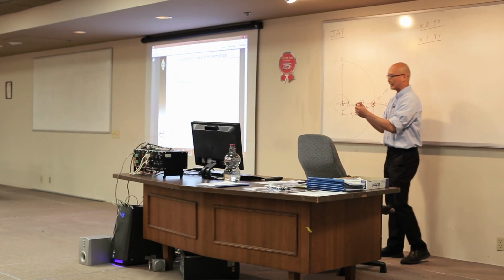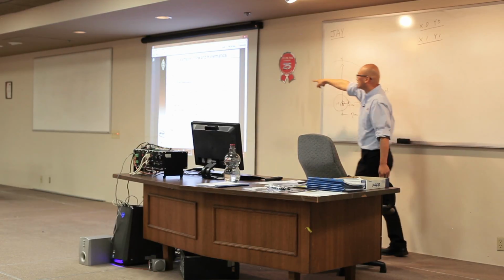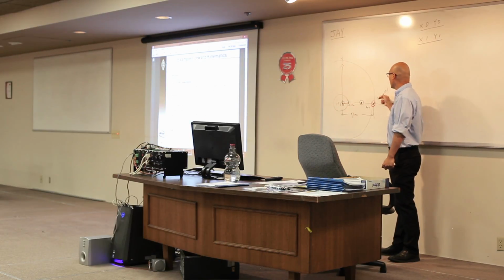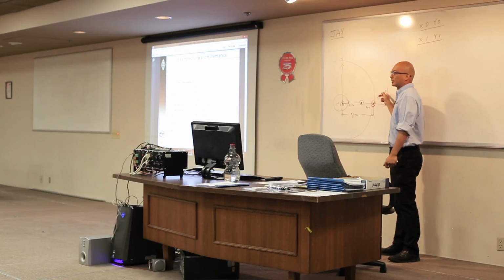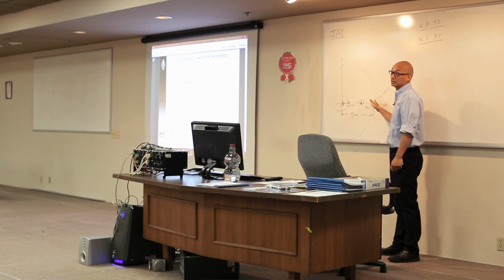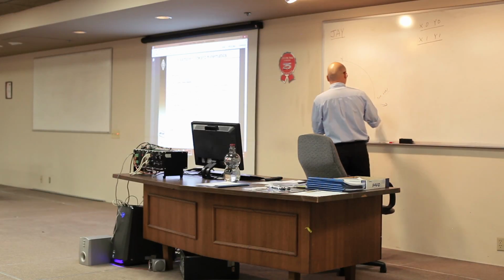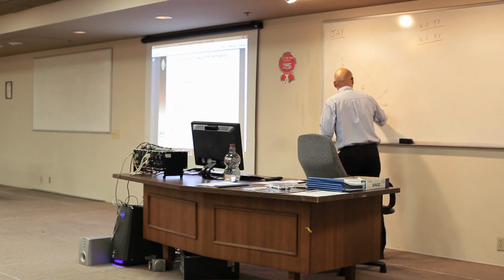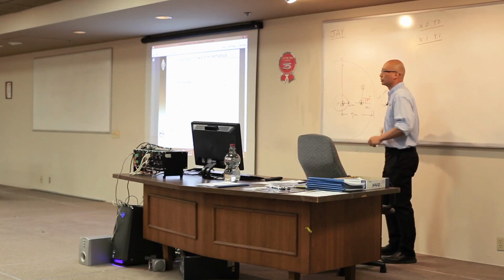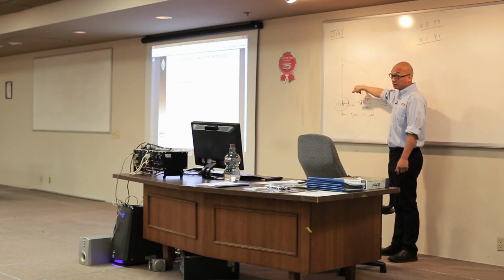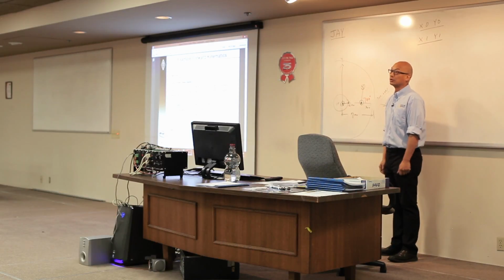Because that's the calculation through kinematics, the floating point. After the kinematics calculation, then I calculate this. This is the result. Although we know that this is okay, for a computer, for a PC, this is not okay because this definitely violates the range definition. Okay? So that's why we put the robot initial position in here, which is adding 90 degrees, to make sure that initially, if your motor is at home, then if you go to 0, 0, something like this, this will be the position that you will have.